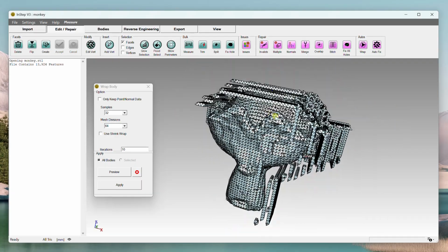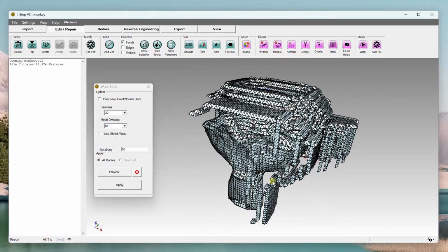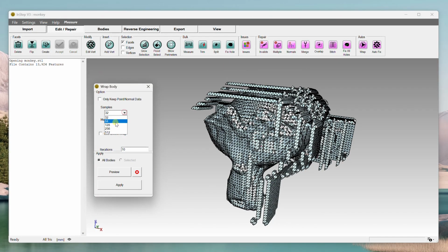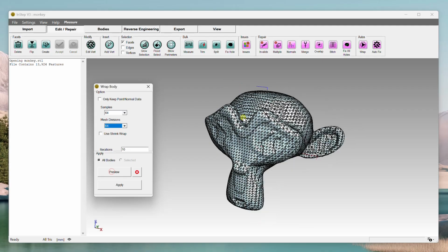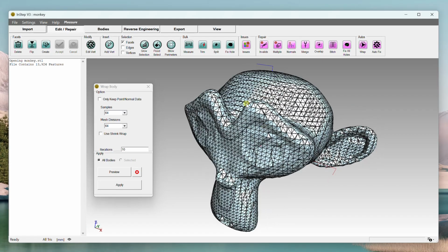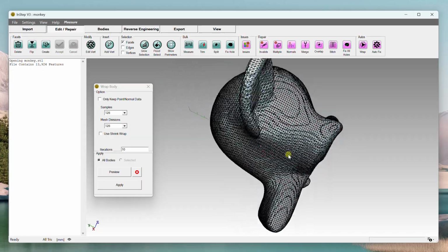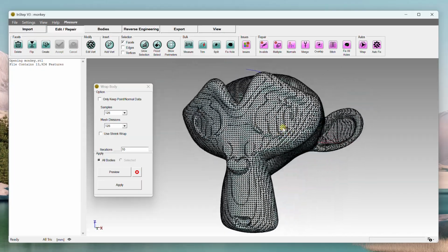So in this case it's very quick actually, where the mesh suddenly grows outside of the original sample set. So you have to start increasing the samples to remove that, and here you might start to get to a level where you can actually use the data already. And there we see again the mesh divisions are too high. Increase the sample rate and we're back to having a relatively good data set.